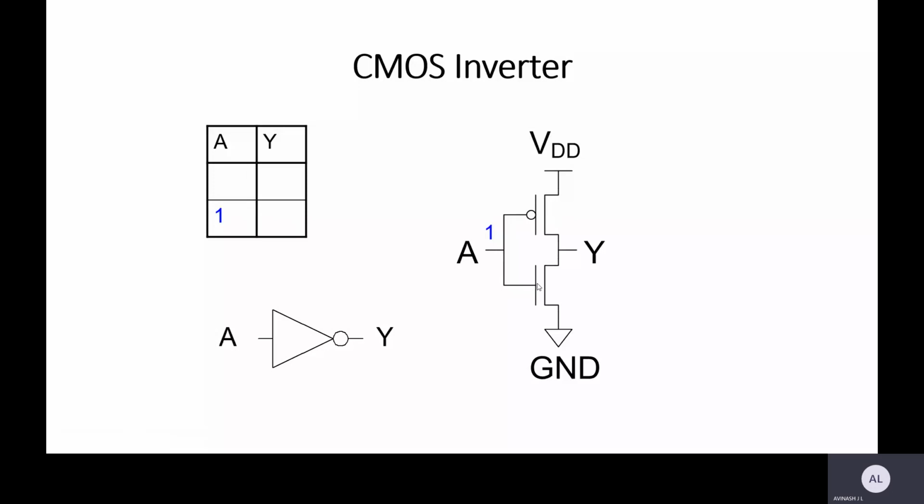When the gate is closed for the PMOS, what will happen? The VDD will not be able to flow. When the current is not flowing, definitely Y will be 0. Y will be 0 even though the NMOS is on. Even though the NMOS gate terminal is getting the supply, the VDD is cut off. That is why we will not get the output. Is it clear to you?